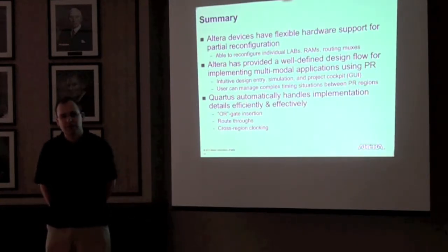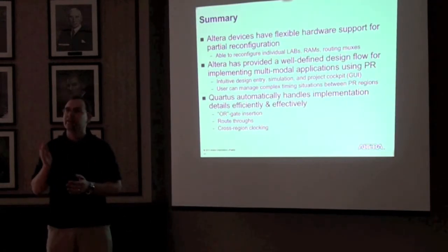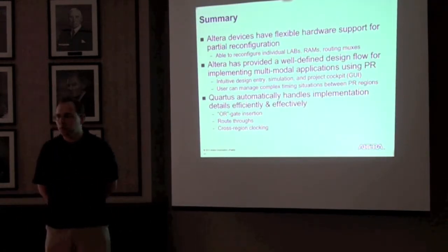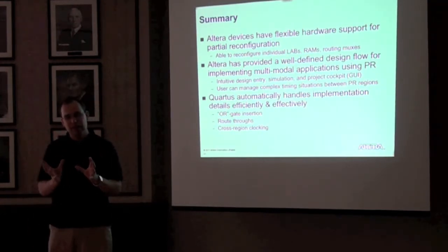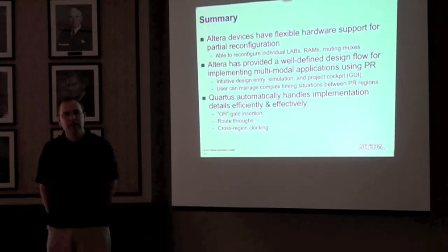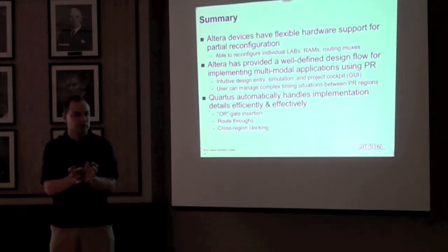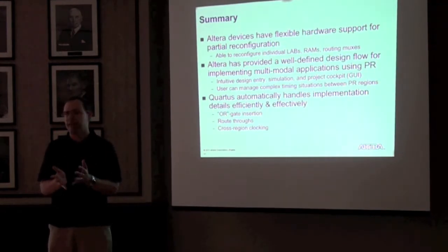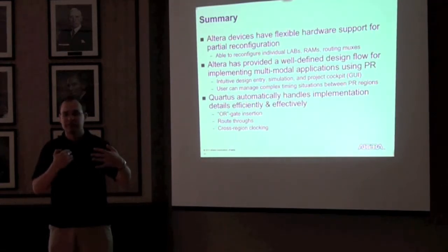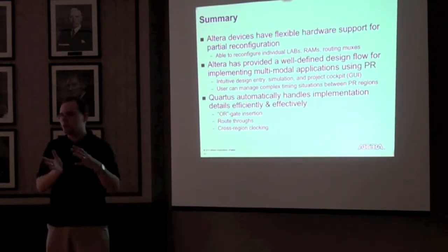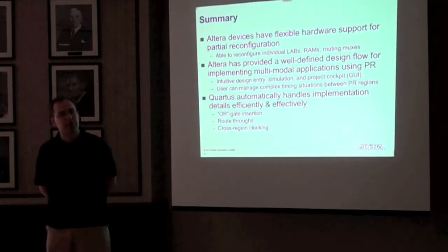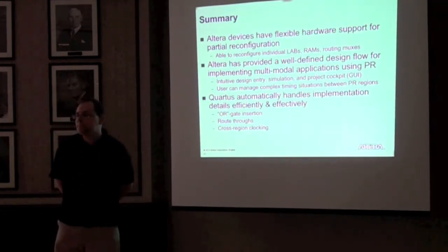So again, this is 11.1, which hasn't been released yet. I think it'll be released sometime in October. This is our first release of the software, so at the current time, the answer is no. That may significantly increase the latency. And again, with the STC file, the user can pretty much control whatever they want. Probably a good design technique is to over-constrain all three regions. I expect a common case is that most register paths will not cross PR regions, but rather, people will likely be registering the boundaries. But maybe not.